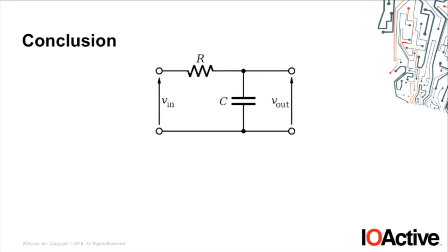It's the same thing. The only thing is that probably there is not much attention on the pure electrical part of the systems. So even though on some data sheets they recommend using anti-aliasing filters, sometimes they are too relaxed and allow you to put like 50 kHz bandwidth. So if you're using a system with a narrow bandwidth, try to put an anti-aliasing filter for that part.